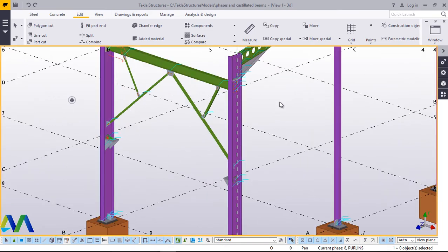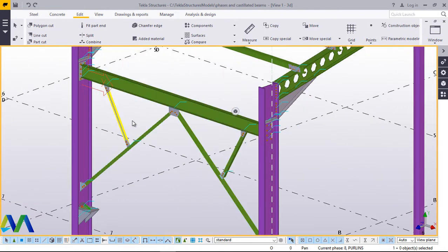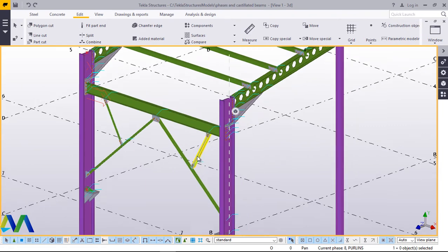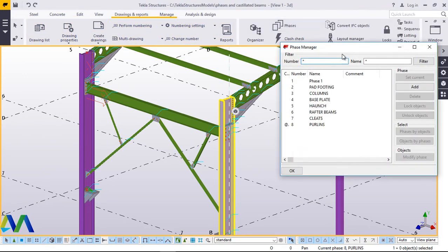Now the thing remaining is now to categorize all these parts in Face Manager, so that when it comes to creating the shop drawings, it becomes just a click, and it's simple as that. Now I'll come to drawings and report. I'll come to Face Manager here, then under Palette, which is our current member here, or current classification of the structure parts.